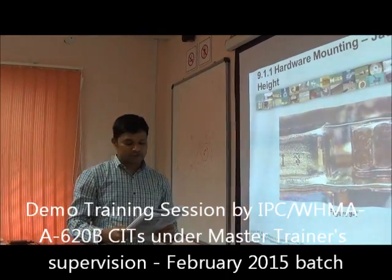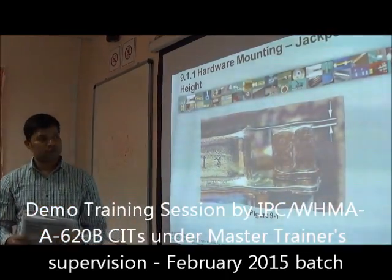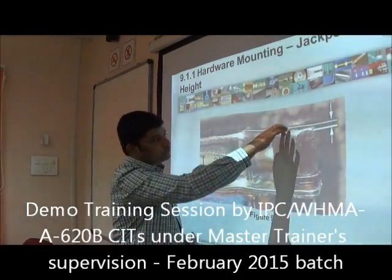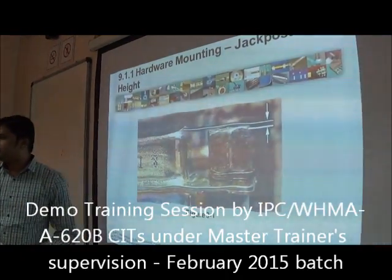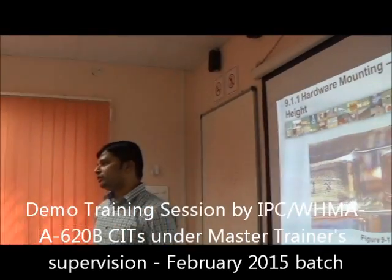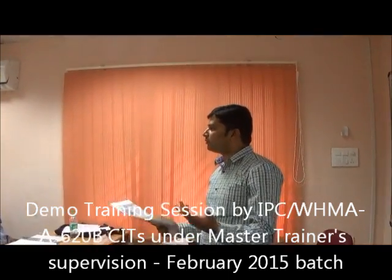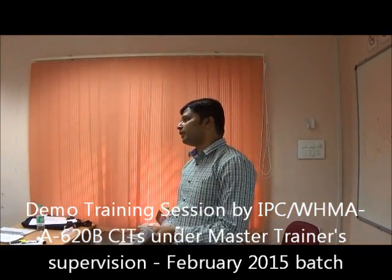So what is the difference between class 1, 2, 3? The face of the jack post is more than plus or minus 0.5 mm. If it is more than 0.5 mm, what will happen? Connectorization will not happen properly. Some of the contacts may get contact, some will not get contact. So we do not get proper connectorization.